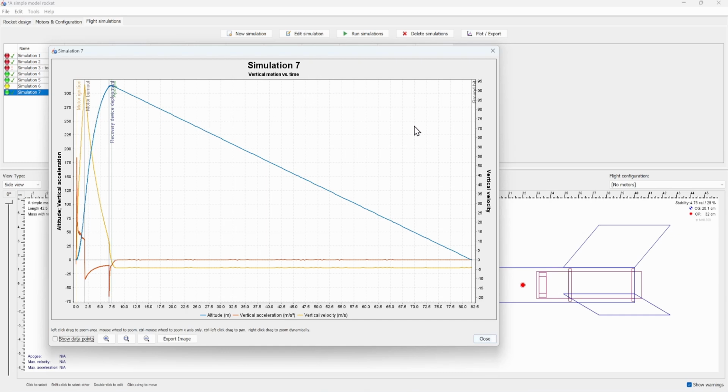We can see on the y-axis on the right-hand side that it went about 90, but if we hover over it at the very top, we can see that it went 91.88 meters per second. Now from peak velocity, we can see that it goes coasting. This is when it loses most of its velocity. From here, while it's slowly gliding down, we can see the descent rate. It's just below -5, which looks correct.